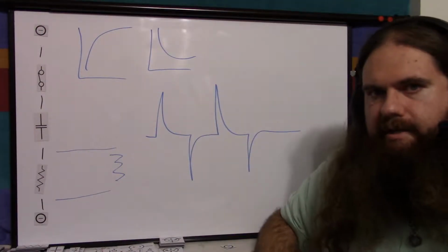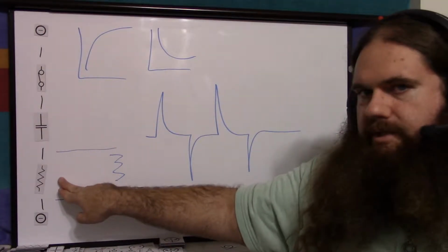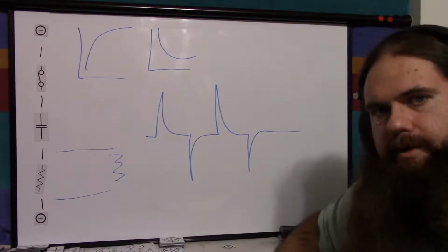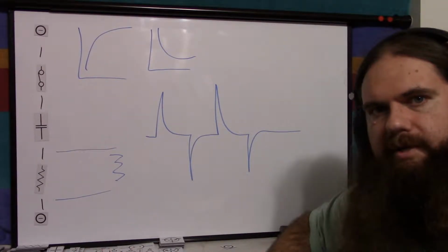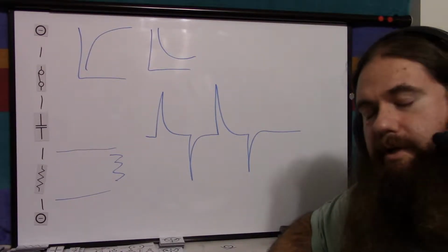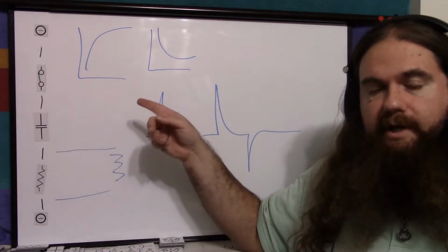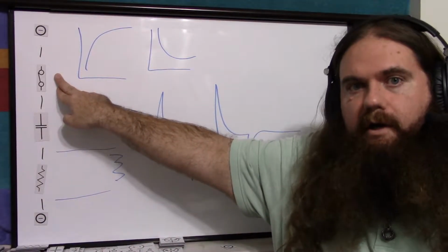This is called a high-pass filter when you measure across the resistor like this. Does that look familiar to you? Remember when I was explaining high-pass filters in Fourier series against a square wave? What is a square wave in this case? Well, we've got 5 volts and we're turning it on and off, on and off, on and off.